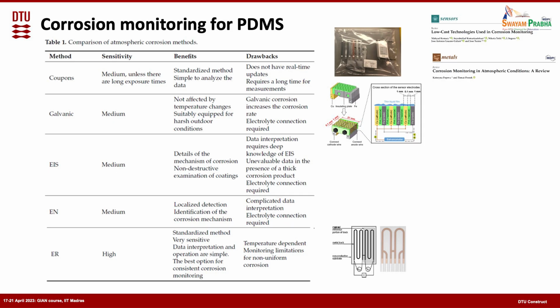There are EIS sensors, which we also have. I didn't put that here, but we also have a sensor which we made, that is an EIS sensor. Basically, we have a pattern like these comb patterns which you saw yesterday, and which measure the impedance along with the temperature and humidity.